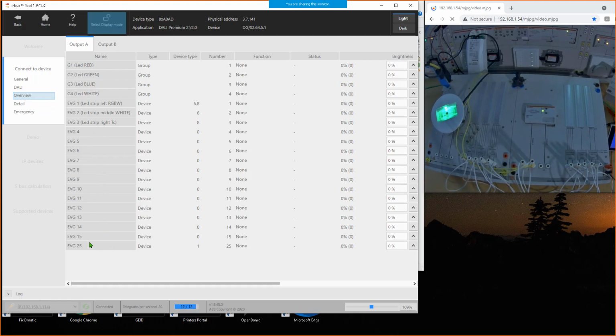But now what is strange, that here my emergency converter appears. You see here the device type. Device type 1 means it's a self-contained emergency converter. This is a special emergency converter, a so-called switchable maintained converter. This is a converter which can also be switched on and off by a command. And then it appears here also in the list like an individual ballast. So it's also possible to switch this ballast on and off here.